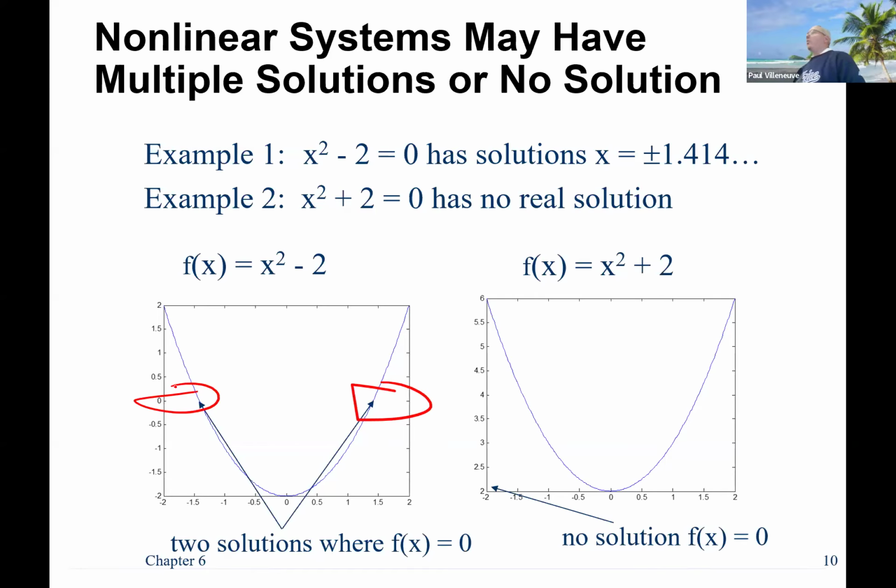Here's a simple case where we have a constant power load, and this is just a simple series circuit. We have a 9-volt battery and a 1 ohm resistor feeding an 18-watt load. So what we're going to do is solve our nonlinear equation, and we know that I squared times R, and that's our load R, has to be equal to 18 watts. My current is 9 divided by that 1 ohm resistor plus the load resistance. Multiply that squared by our load and set that equal to 18 watts.